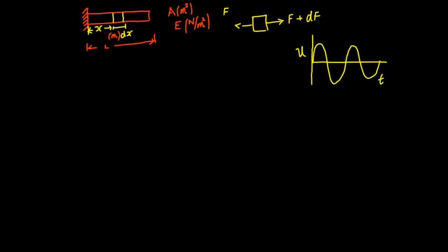All right. Now, what is the net force? That is the net resultant force, which will be F plus dF difference F, and that should accelerate this particular small object. So that is given by Newton's second law, which is mass times acceleration. So this F and this F go away. So the net force, which is represented by dF, should accelerate this small mass. Well, I should not be calling that m, because it is a small mass. Maybe you may also want to use del m, but I'm just using Newton's second law notation.